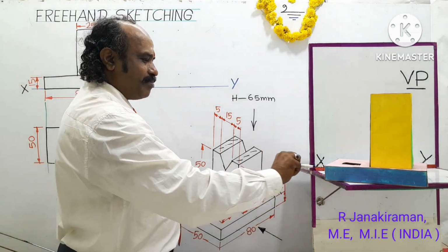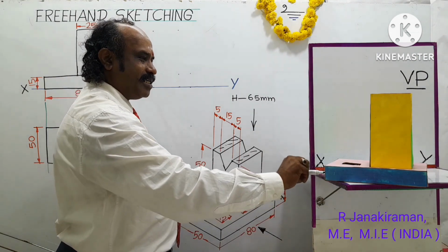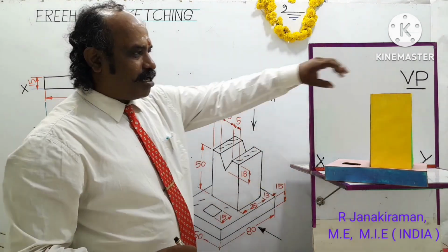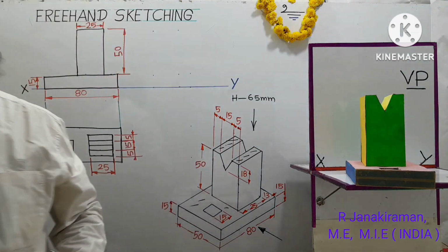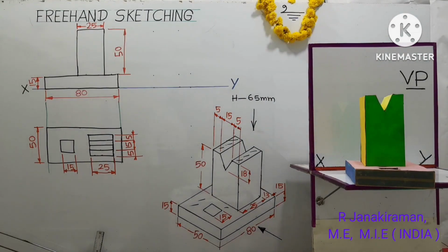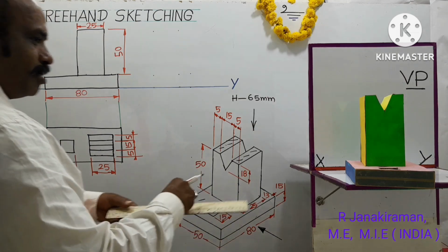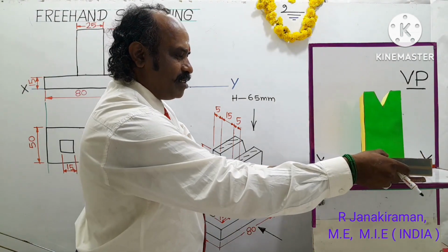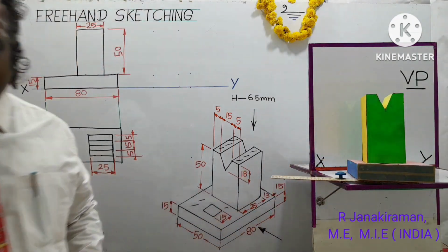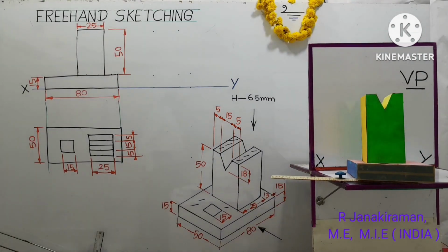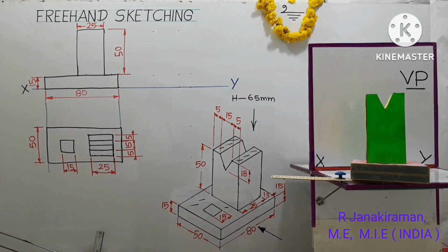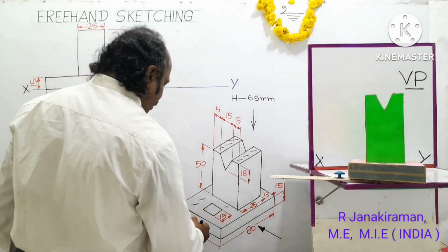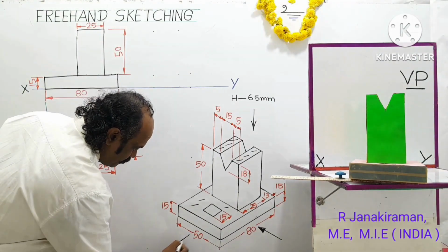Looking in this direction, the observer can see the breadth of the object and the height of the object. So I turn the object so that you can see it in the camera like this. The portion visible to the observer will be the breadth of the object. As I told earlier, this breadth shall be seen. And the rose color part on the top surface of the base will be merged, forming a single top edge here. These are the portions visible to the observer. Looking from this side, we call it the left side view.